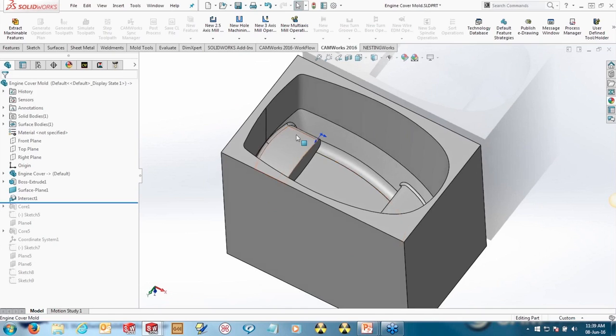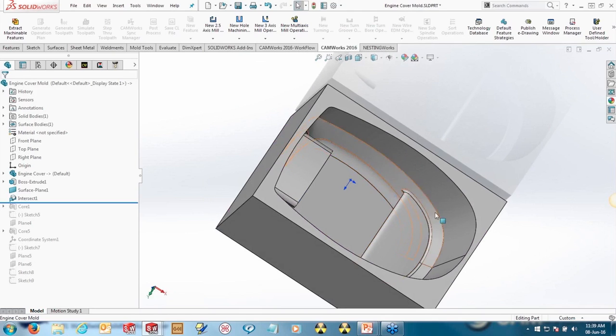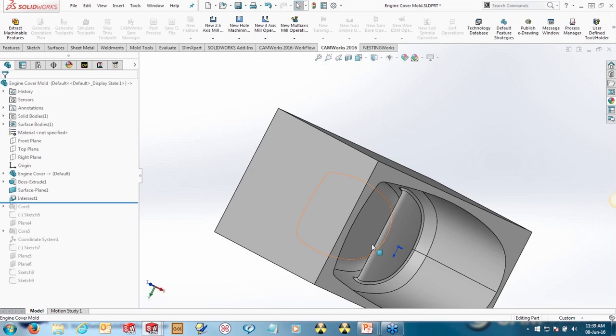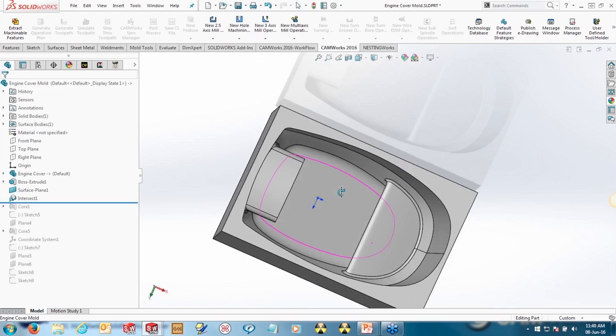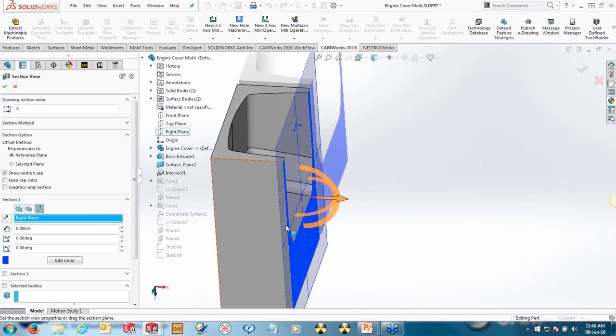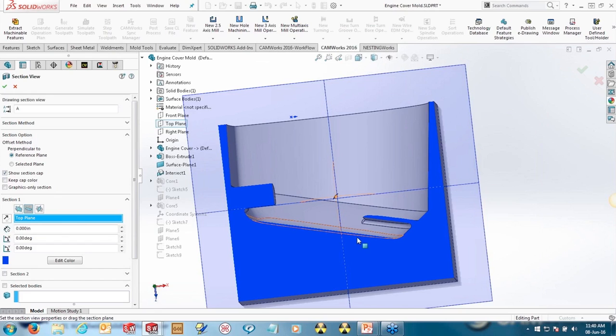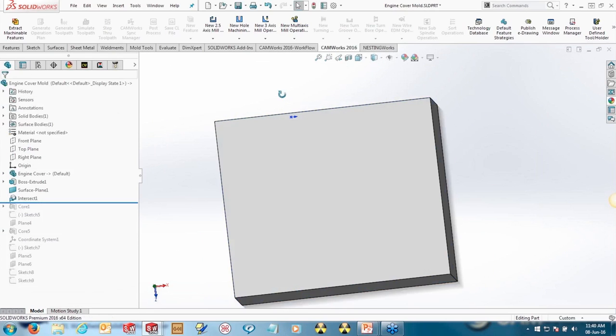In this case, because we've got this vent over in here in the mold, we've got to create some sliding cores for this mold, because obviously I can't get down here and start machining underneath that lip there. So if we go on the other side over here, you obviously can't get your tool down here and start putting stuff in there. So we've got some sliding cores that we need to worry about.